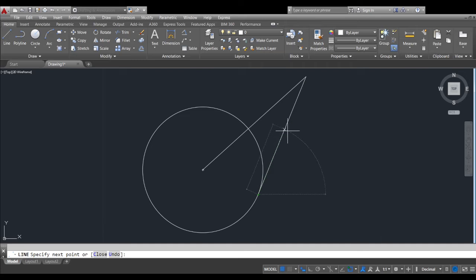So, if we want to locate the midpoint right away, we can type mid and enter. So, here is our midpoint. To turn the O-snap on and off, we can press F11. However, if you are in the middle of a command, or a certain command is in progress, F11 is not working, no?